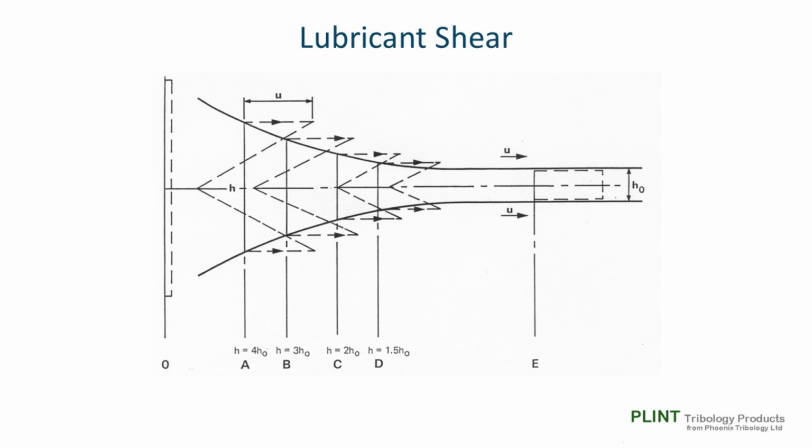If the response of the lubricant to this combination of shear and pressure is non-Newtonian, that is, if shear stress ceases to be proportional to shear rate, it may be expected that its behaviour in the approach region will differ from that of a Newtonian fluid of the same nominal characteristics. It is this act of shearing that gives rise to loss of apparent viscosity in polymer thickened oils and limits the usefulness of viscosity index improvers.